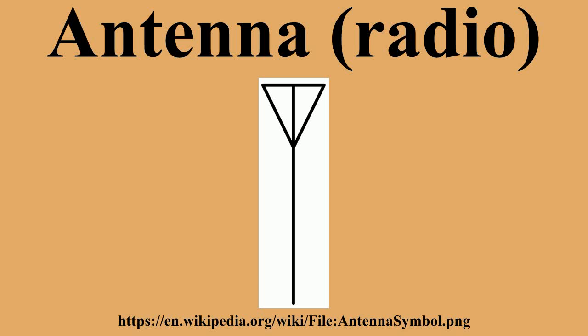An antenna counterpoise or ground plane is a structure of conductive material which improves or substitutes for the ground. It may be connected to or insulated from the natural ground. In a monopole antenna, this aids in the function of the natural ground, particularly where variations of the characteristics of the natural ground interfere with its proper function. Such a structure is normally connected to the return connection of an unbalanced transmission line, such as the shield of a coaxial cable.